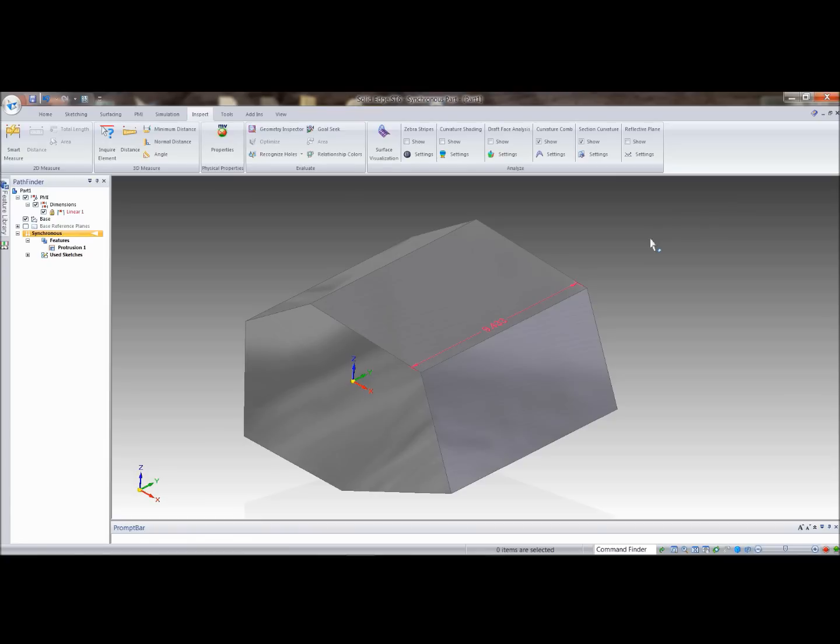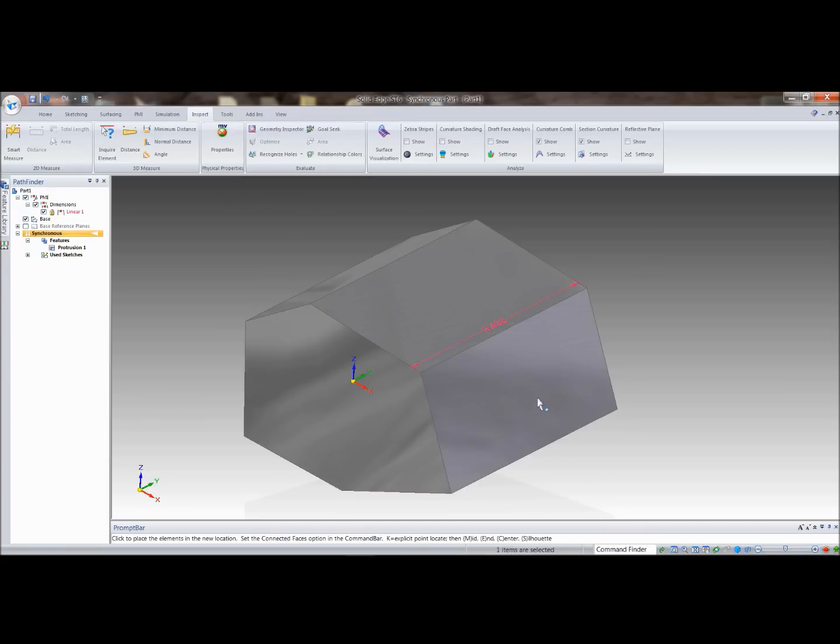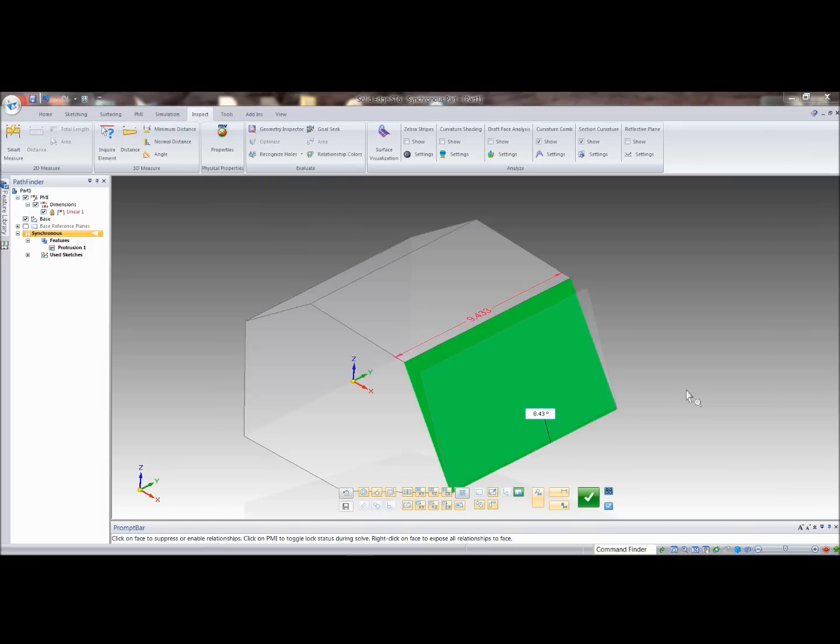So I could go and change the material and rerun this. If I changed it to iron, which is a more dense material, this block would shorten up after the goal seek is completed. So that's a very powerful tool, and I'm sure you'll find lots of uses for it. I can change the size of this by changing perhaps the angle of this face, and just by doing this I have changed the size of it. It's going to be smaller, so it should get a little bit longer to achieve the 60-pound mass.